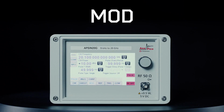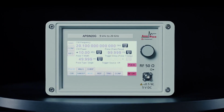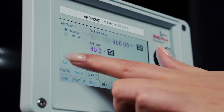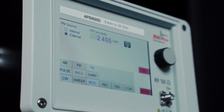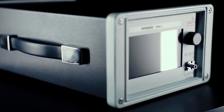Then we go to the modulation menu. You can select the type of modulation: pulse, analog, and LFM chirp button. The analog modulation button has a submenu with analog modulation: AM, FM, and phase modulation. All types of modulation are standard and are not optional.